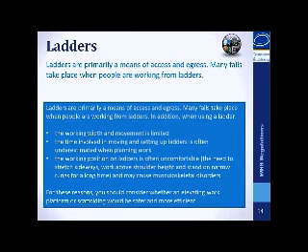Ladders. Ladders are primarily a means to access and egress. Many falls take place when people are working from ladders. In addition, when using a ladder, the working width and movement is limited. The time involved in moving and setting up ladders is often underestimated when planning people's work. The work position on ladders is often uncomfortable, and the need to stretch sideways or work above shoulder height and stand on narrow rungs for a long time may cause musculoskeletal disorders.